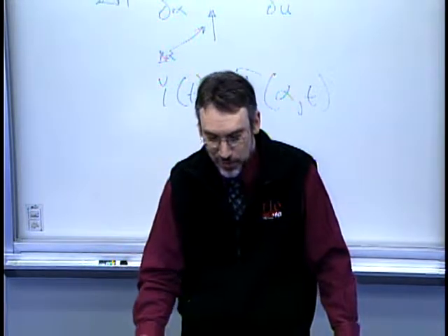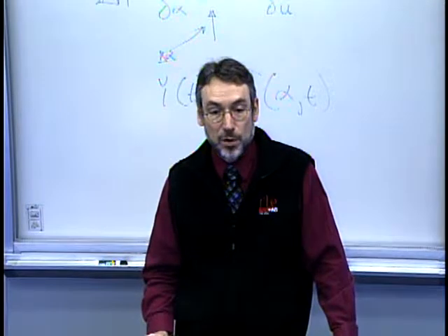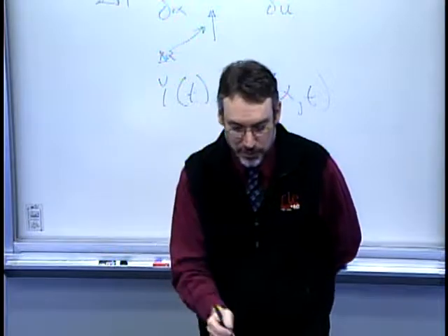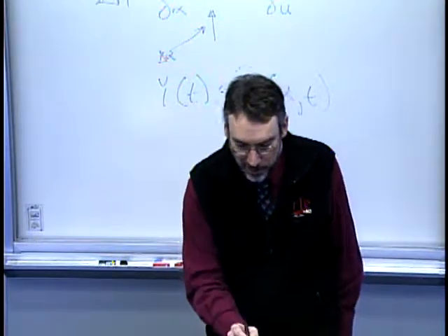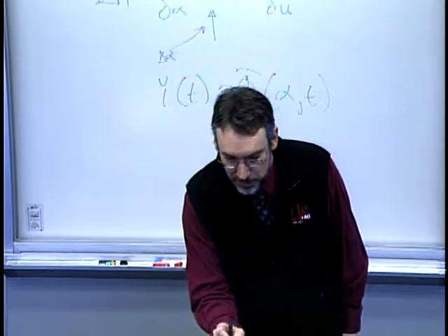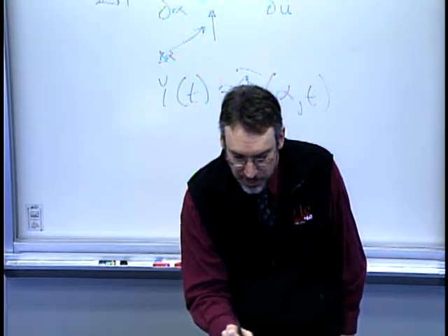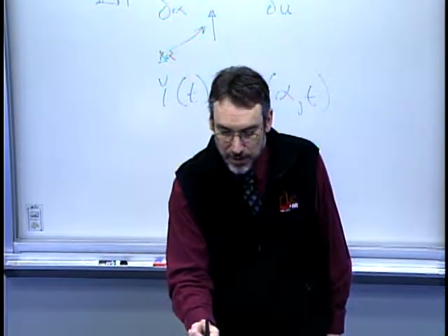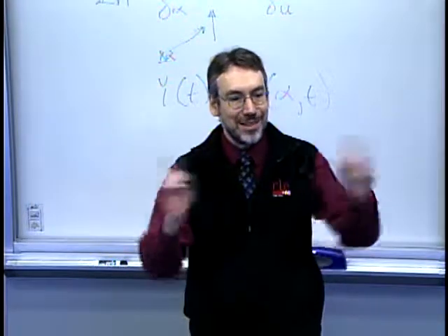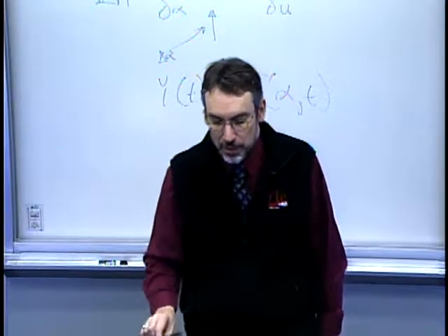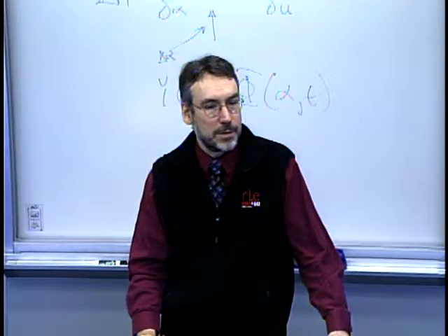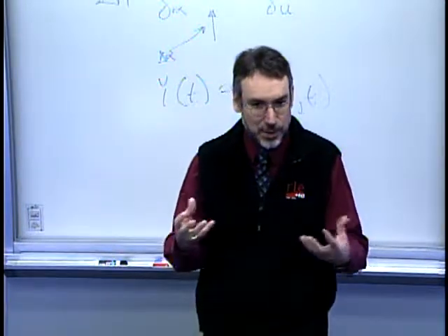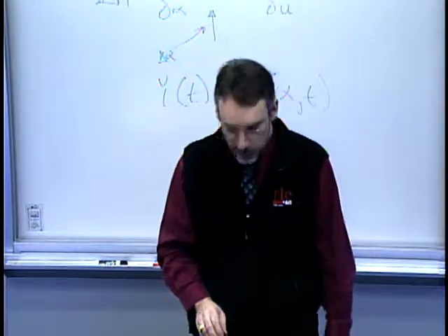Yeah, so that's actually a very interesting point when we start talking a little bit more about design of experiments, about the synergistic effects. It may not be a simple additive model. You're saying as we go here from 5 to 10, we got an increase. Here when we went from 5 to 10, we got a decrease. So the effect of holding time may be completely in the opposite direction at two different pressures. Very good point. So that means there is some strong interaction between those two, or mutual dependence between those two parameters.